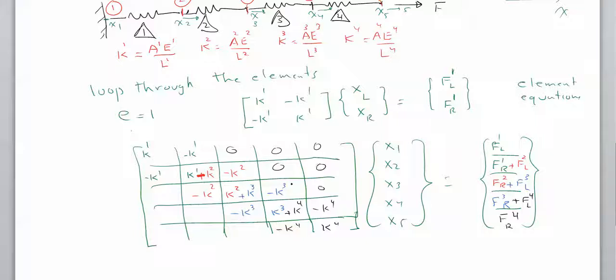And as I promised you, the stiffness matrix, and the mass matrix, which we don't have here, are going to be sparse and symmetric. You can see this is symmetric. Now, what do we know about the restraint? We know that x1 is 0. That's pretty much all we know, which means that the corresponding entry on the right-hand side is the reaction force at the wall, R1, which is an unknown. X2, X3, X4, X5 are all non-zero, and our job is to find them.